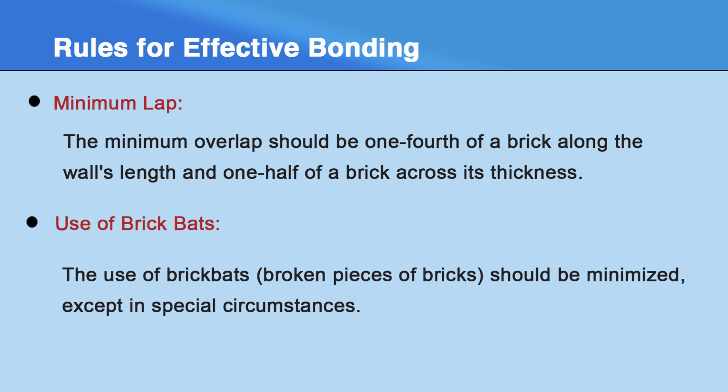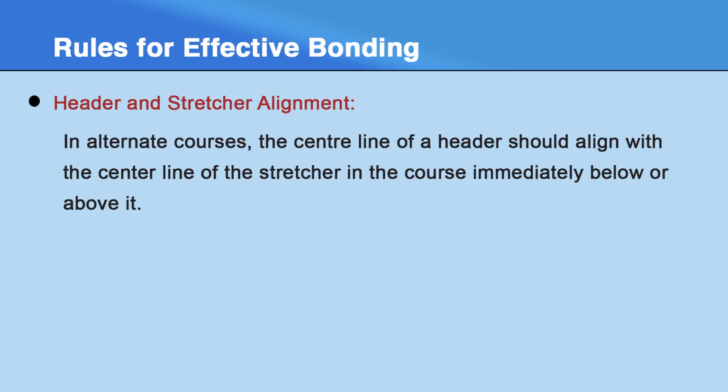Next point is the use of brick bats. The use of brick bats is nothing but the use of broken pieces of bricks. So, these brick bats should be minimized except in special circumstances. As far as possible we should use the complete bricks, and only under special circumstances can we use the broken pieces.